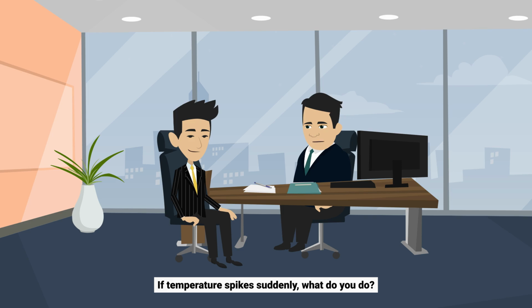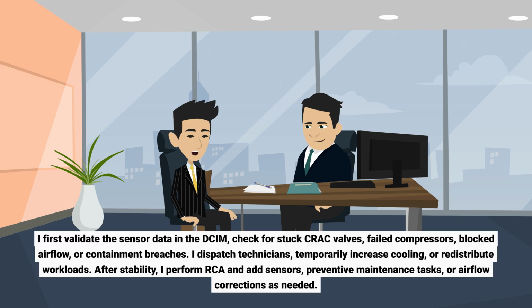If temperature spikes suddenly, what do you do? I first validate the sensor data in the DCIM, check for stuck valves, failed compressors, blocked airflow, or containment breaches. I dispatch technicians, temporarily increase cooling, or redistribute workloads. After stability, I perform RCA and add sensors, preventative maintenance tasks, or airflow corrections as needed.